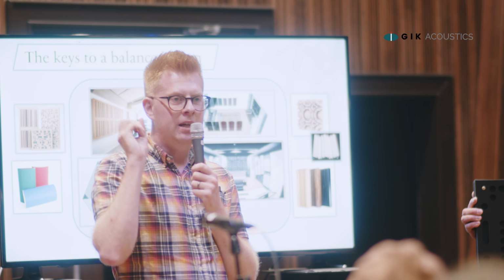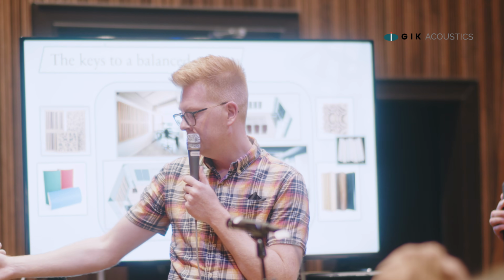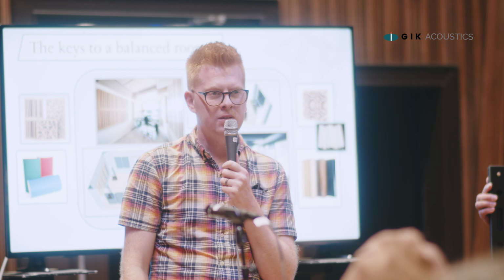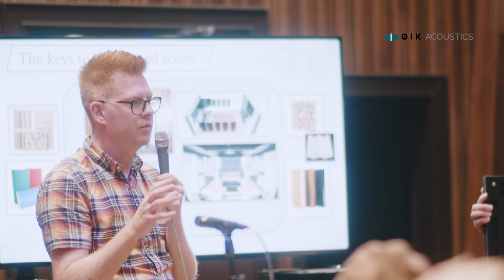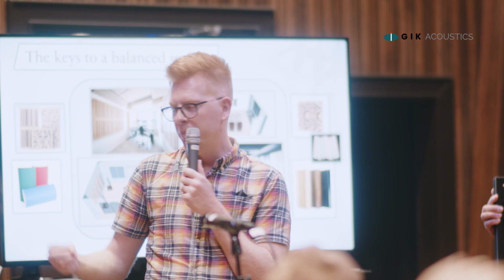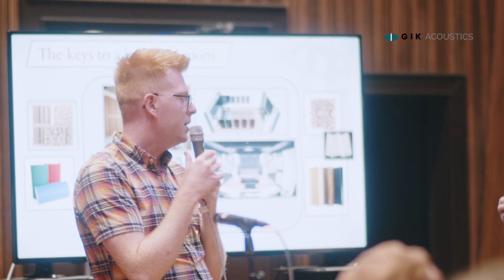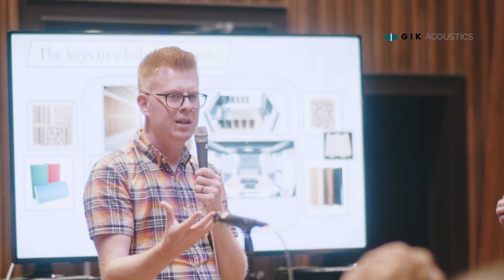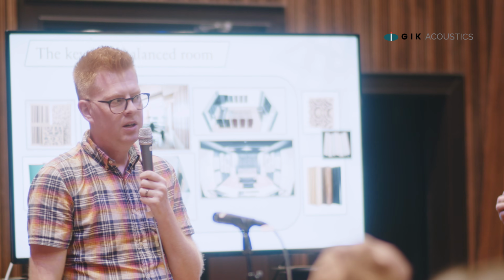So they're still primarily absorbers, actually, even though they have these reflective surfaces on the front of them, but they're cut in a way that the majority of the mid and low frequencies is just going to go straight through into the absorbent material behind, but the scatter plates on the front are just enough to provide some high frequency reflection, which is where the clarity is, so that the room starts to sound a little bit more natural again.